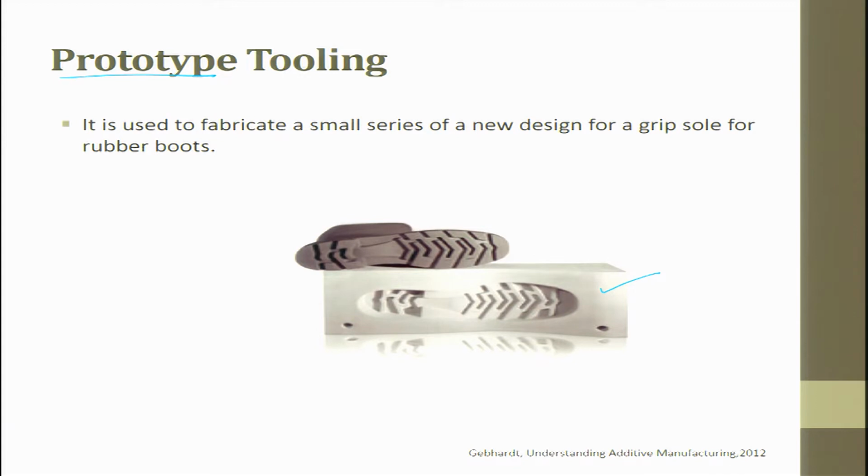You should also understand, making a tool for mass production is expensive. So, only for that we talk about the concept of prototyping of tools. So, here the tool is made as a prototype, and after this the corrections will be made and the final design will be accepted, and directly this tool will be produced. That is called rapid tooling.